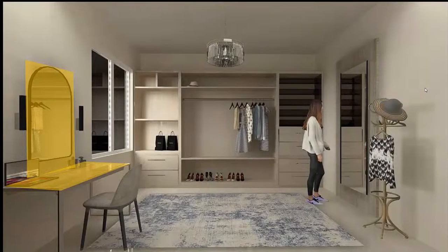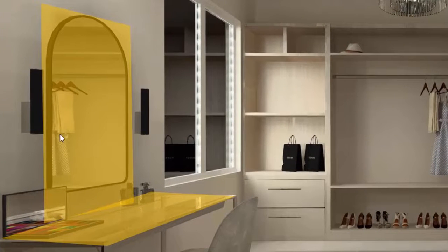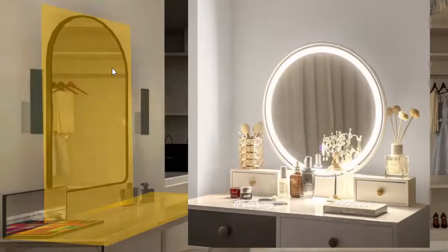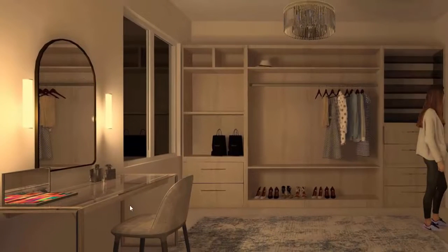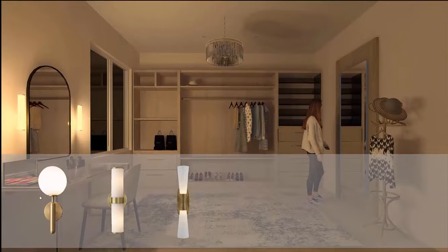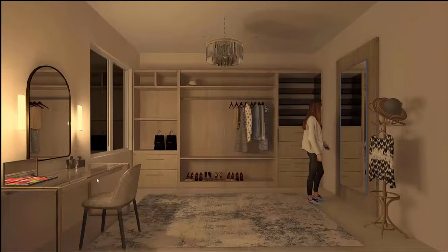Now third task area for us is the dressing unit. In the dressing unit too, I can subdivide it into other 2 more task areas. One is this mirror, and other is this table itself. For mirror, you can opt for mirror lighting, or you can use a wall sconces next to the mirror. Make sure the wall sconces which you are selecting is a diffused source. Okay, something like this. And for the task lighting on the table, anyway we are using this adjustable downlights here.